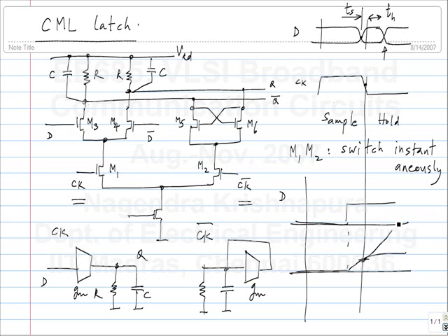Okay. Now, as you bring the step closer and closer to the clock edge, the initial condition gets smaller and smaller for the regeneration phase. So, it may not regenerate. So, what does it affect? It affects the setup time. So, there is a minimum amount of time before the clock falls negative, during which the data should not change. If it changes, the output also tends to change, but it may not change completely.